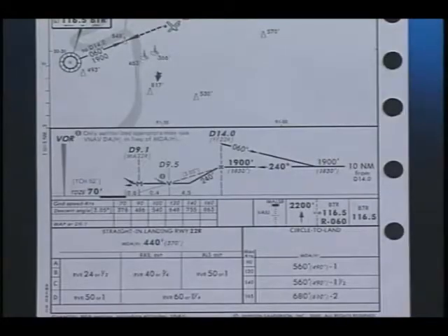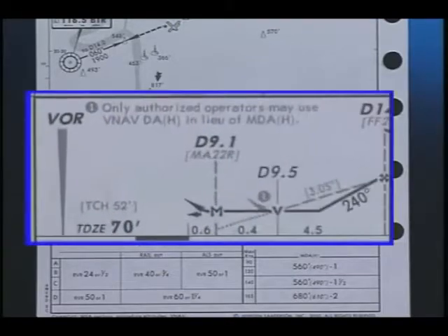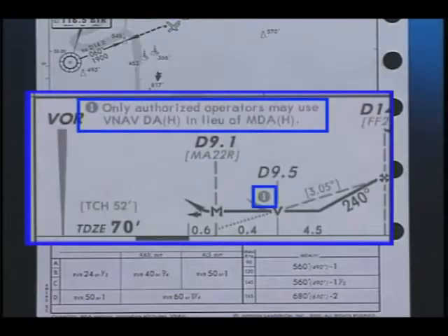One very important change to the profile view is the appearance of notes on some non-precision approaches. In the profile view of this VOR DME approach, you see a ball flag and a note stating, "Only authorized operators may use VNAV DAH in lieu of MDAH."